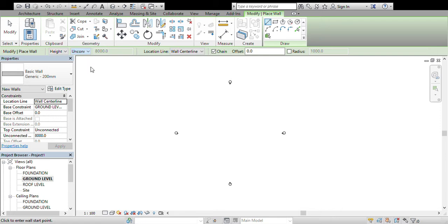It means it will go up to roof level. You see, up to roof level. Then after that, I'll come to set this wall. I want to make some settings regarding this wall. Click edit, and here you can duplicate. Duplication means you can put properties into this wall without disturbing other walls. It means this wall will be unique. It will be different from others.